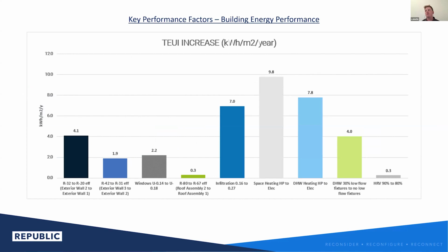That specifically speaks to air tightness, air sealing, and ensuring we've got control over what air enters and leaves the building. Based on the development and rollout of this building typology across multiple climate zones and locations in Canada, we found that this has really been the single largest factor in reduction to thermal energy demand intensity, and that's really focusing on infiltration rate.